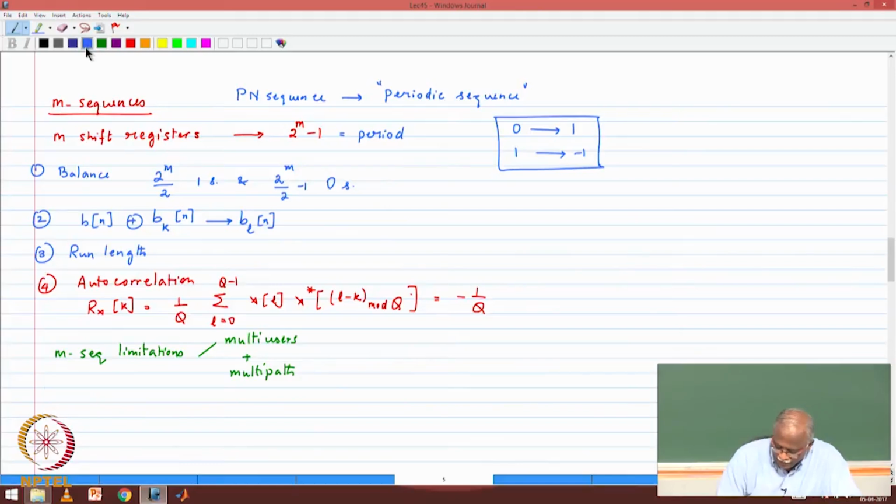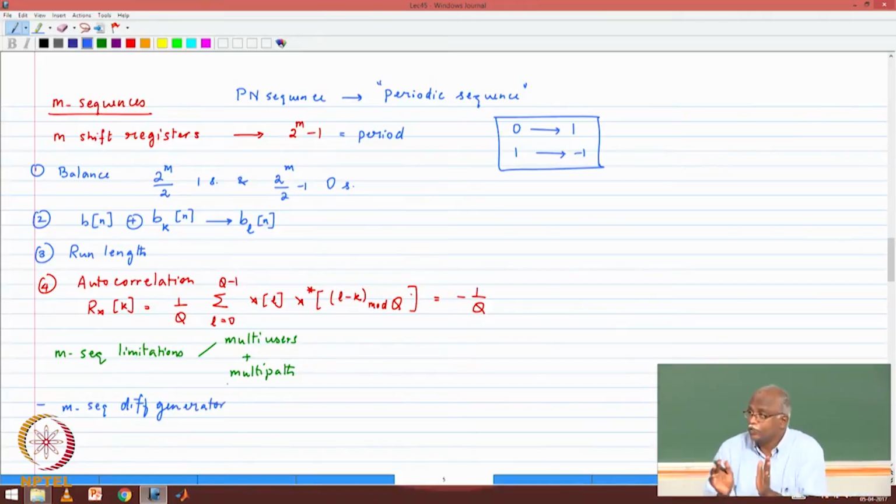We also said that if I take M sequences from different generator polynomials, there are good sequences available, by the way. You can get good correlation, but you want a large number. You want to have, let's say, 32 users, and finding 32 sequences from different generator polynomials, all of which have good correlation properties, is going to be the challenge. For different generator polynomials there is no guarantee of the cross correlation. So you have to check and see if the cross correlation is okay.